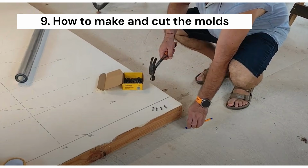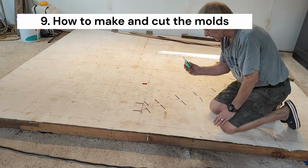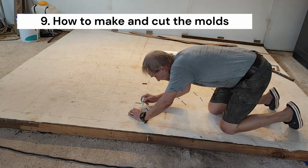The standard method is to use nails. Bud McIntosh used halfpenny nails with the rather large head pointing inwards, each with its head precisely located on the line. Give each head a hammer tap to set into the plywood and make it stay. Usually some nails won't stay. A method to fix this is to use Loctite in the holes.